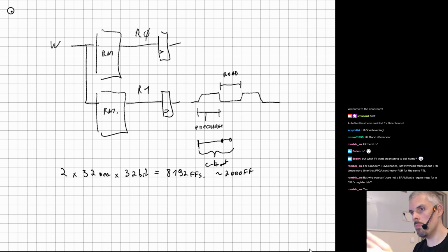It will distribute it sort of organically, a little like it wanted. That's not necessarily optimal. So what I wanted to do is, first, concerning the regular structure, use a Python script to manipulate the design to manually arrange the flip-flops in a structure that makes sense inside the design itself. And secondly, instead of using flip-flops, use a latch.